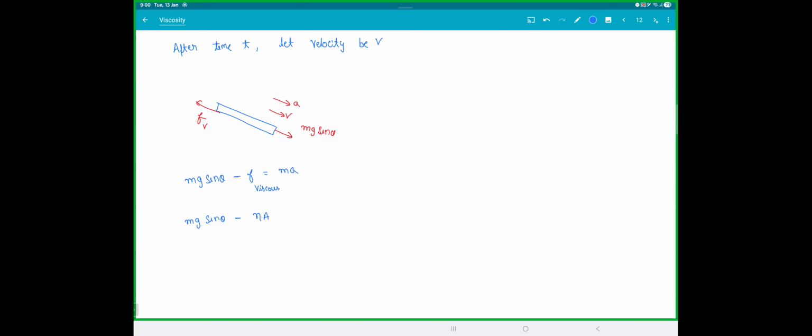So you're taking velocity between these 2 points basically. When you take the thin layer, this is the fluid between them. This point is going with v, so that layer is also going with v, and this point is going with 0, and the distance between them is z. So dv by dz will be v minus 0 by z minus 0, or v by z. Because it's a thin layer, you can do that.